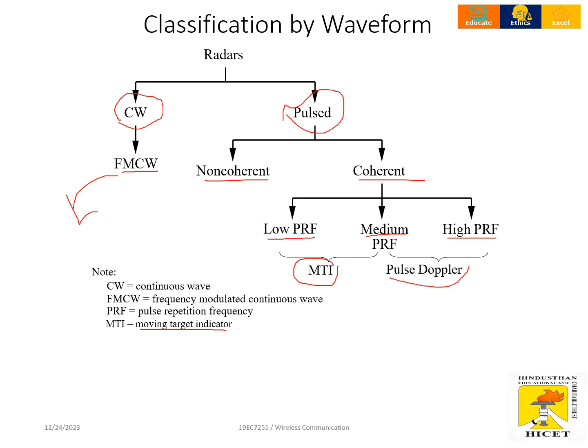The next is pulse Doppler. If there is any change in the frequency, if it encounters any Doppler effect, we have to prefer this PRF. Or else, if it keeps on moving, we have to choose the low PRF. Repetition means: this is my radar antenna, and the generated waveforms will be like this, it keeps on sending the waves.